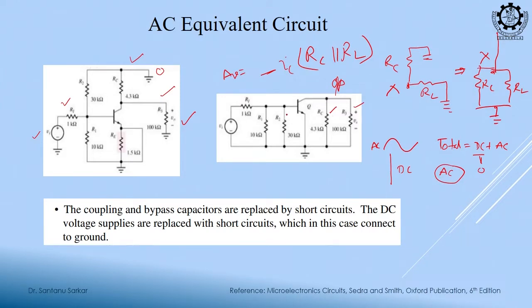At the input side what is happening, you see now R1 and R2 come in parallel, but in the complete DC circuit it is not, right, because now it is redrawn so that this node is grounded. So, this node and this node come in parallel, both are grounded. So, I have to just redraw the circuit, that is it. So, it is also redrawn. So, what is the equivalent resistance at the input side? Similarly, R1 parallel R2, that way we will simplify the circuit.